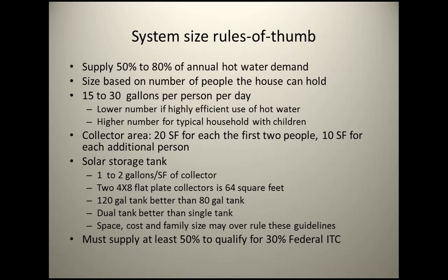What level of insulation do you have in the tank? These are generally R17, R19. One of the most cost-effective things you can do is put a blanket on the water heater. Very, very cost-effective, and the blankets are like $30. Conventional water heaters are not particularly insulated, and if you put a blanket on just your conventional water heater, the return is fantastic.